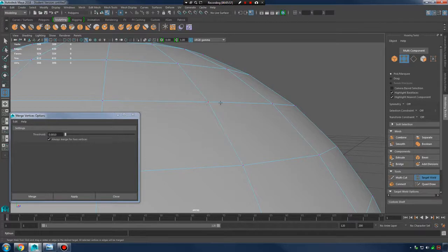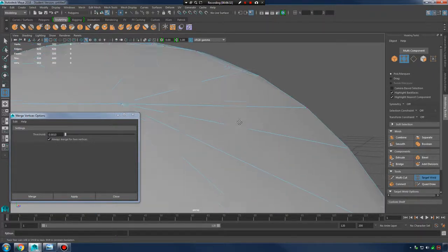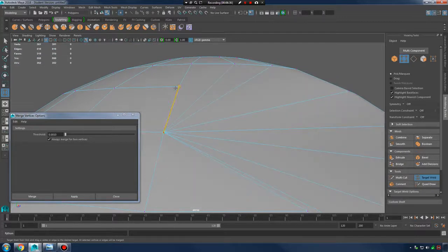So what I'm doing is I'm left clicking a vert and holding down the mouse button, and we get this orange circle. When you let go of the mouse button, that orange circle goes away. So let's see, how can we use this tool in the same way we were using the last two to merge our vertices together? Well, with my left mouse button held, I click and drag to another vertex, and we get a line blasting straight down here. And when I release, it merges.